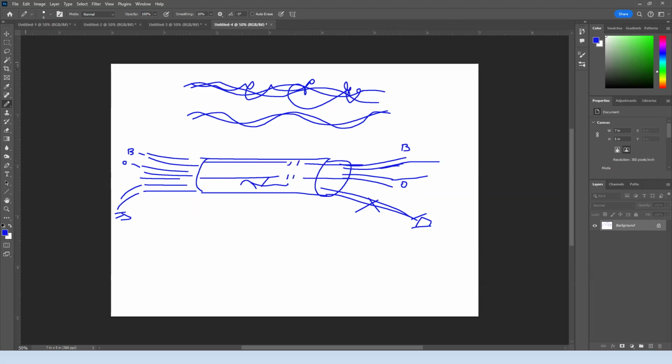But in this case you are losing the twist, because this pair is twisted around itself, the other pair is twisted around itself, and those two conductors are just like two straight wires to each other. So that's splitting pairs. You use one conductor from one pair and another conductor from the other, and do the same thing on the other side in order to give the client some connection.